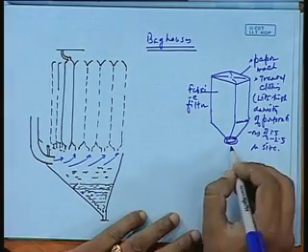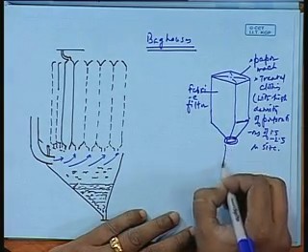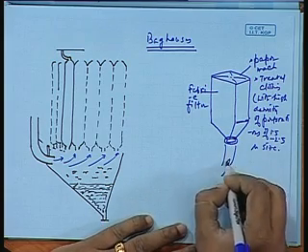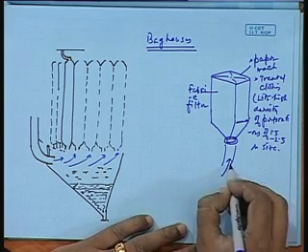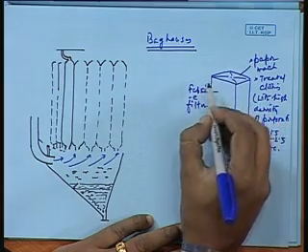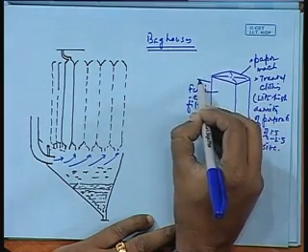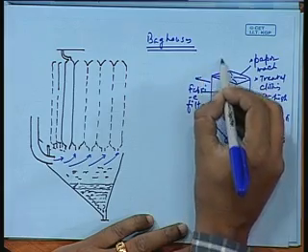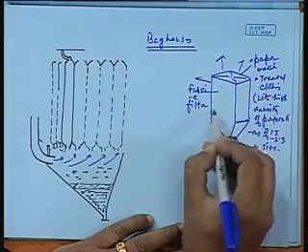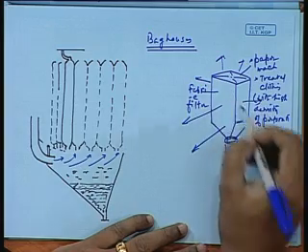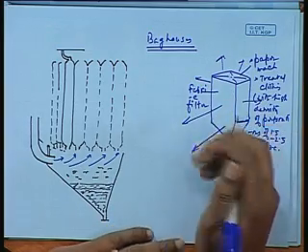So what is happening here is, as in a vacuum cleaner, the air is sucked in as dusted air. The air passes out through the perforations, and the particulates are arrested on the bag itself.